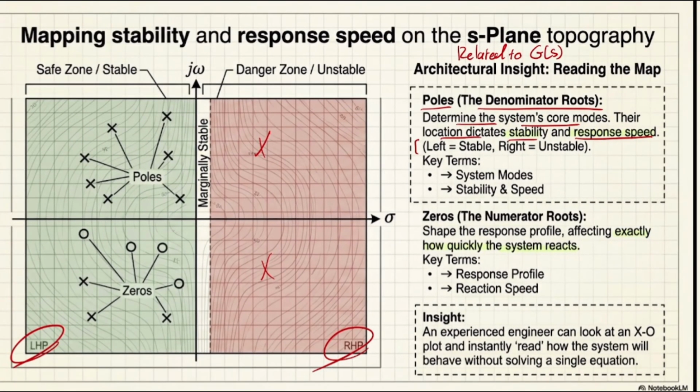The S-plane is just a normal plane. Previously we had X and Y, but at this point we have the real axis and the imaginary axis. These are based on your poles and zeros, because when you talk about a second order system, you are dealing with s to the power 2, and not all the time are the roots of your equation going to be real numbers. Sometimes they're imaginary numbers, as you all know. These imaginary numbers need a place in order to be located. That's why we have the S-plane.